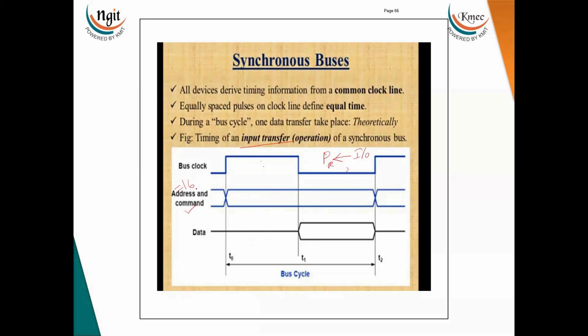Instead of that, all 16 together we can represent by a bus like this. This is called a bus. Here, if I say the address is 16 bits, it means A0 to A15, total 16. Now for this address, how can I represent it? 4 bits together is a nibble, and we can indicate it as a binary equivalent BCD value.